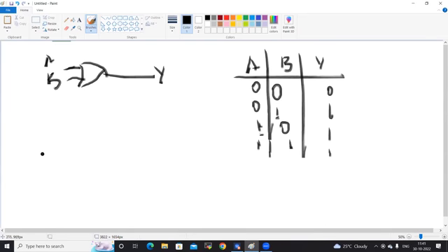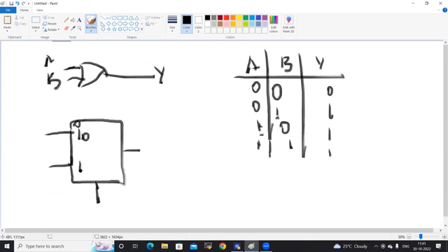Okay, then now we will draw the mux. We'll draw a mux which has two inputs because we are using 2x1, and select line 1, output is 1. This is I0 and this is I1. We are just defining the names of the lines. What I said before is we have to consider this A as the select line always. And now we have to take these two combinations.